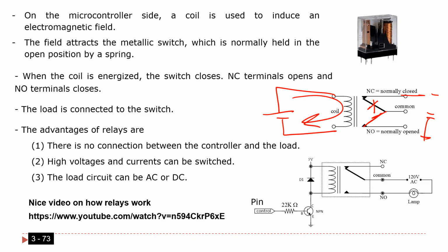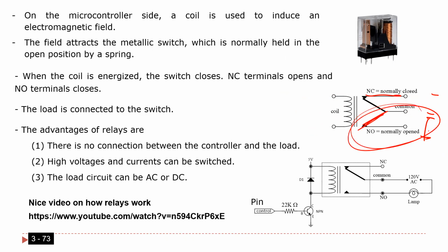What is interesting here, as you see, guys, is that it's like a switch. You open or close. This switch is closed, but I can open it, very simple. We have another switch here. This switch is normally open, but I can close it. How can you close it? Very simple. All you have to do is energize this one. It becomes a magnet and it's going to pull it. That's why when you use this relay, you will hear some tick, tick, tick, because the contactors are going to connect here. Okay, this is what's called the relay.